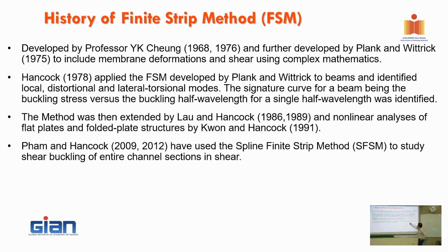So with this one, that publication is the first one in the world. We're lucky to publish and introduce the shear buckling of the whole section. So you imagine, in hot rolled steel or even in cold formed steel, before that, normally with shear, we just look at the web panel, isn't it? When you design any I section or C section or whatever, to check for shear, normally you just take the web panel only, because shear is carried by the web mainly.